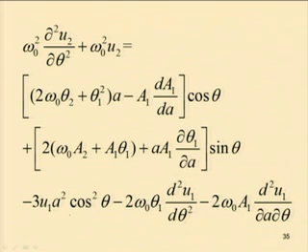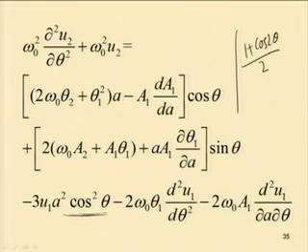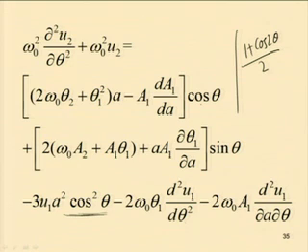In this case we can substitute for cos square theta. In terms of cos theta we can write cos square theta as 1 plus cos 2 theta by 2. So, we can substitute that in this equation, and similar to the previous case, the coefficients of the terms containing cos theta and sin theta should be eliminated to eliminate the secular terms. Otherwise, these terms will lead to the infinite response, which is not practically possible. So, one has to eliminate the secular term.